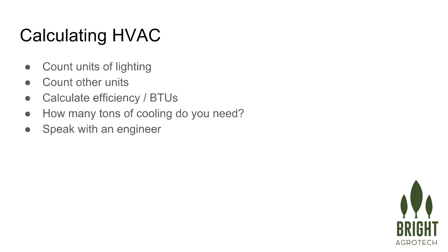Yeah, so with all of these different things, the efficiency rating is basically how well this device translates electrical energy into, for a light, light versus heat, right? So say a 1,000-watt HPS light may be 20% efficient. So it's emitting 200 watts as light and 800 watts as heat. Okay, so I think this is important, right?